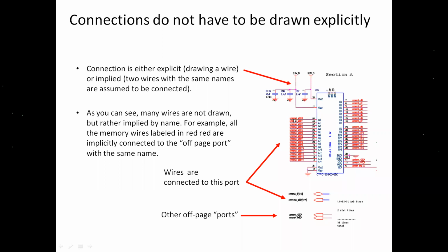If you want to make the same connection on another component, like transistors or relays you are using nearby, you don't want to make wired connections. Instead, you can use the label, so the tool understands that those connections are the same, provided you give the same clear name as pin number 44. So the tool understands that both are connected together.